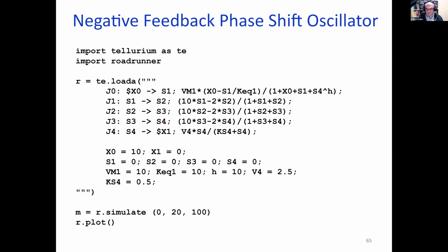It's supposed to do the opposite. But if the phase shift is out by at least 180 degrees, the opposite happens. So when S4 goes up, the negative feedback now does the opposite because all the phases are out, and it starts to increase it instead. And that's actually the source of the oscillations.